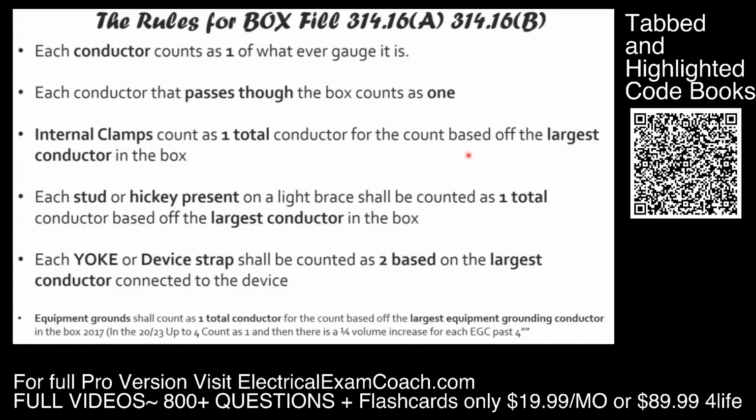Now in the 2020 and in the 2023, it's a little bit different. Up to the first 4 conductors, it's going to count as 1. Then for every one that is past 4, you're going to increase it by a 1/4 inch volume.